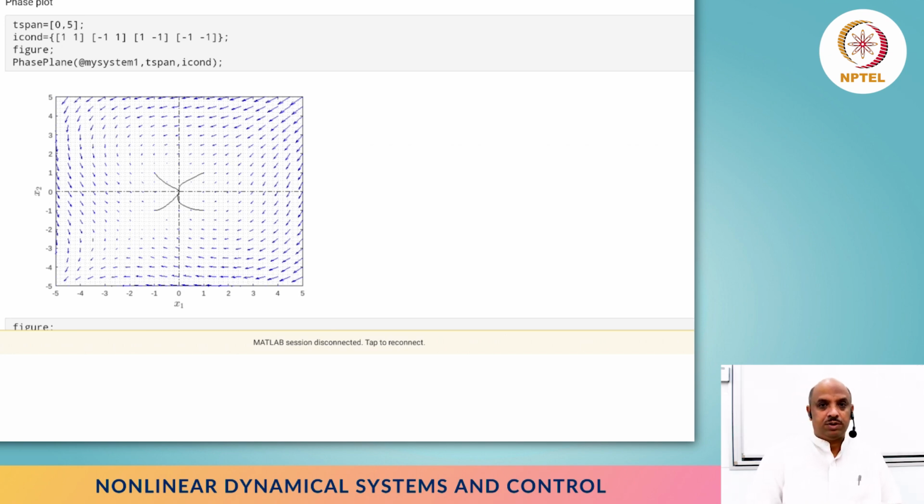If the linearization gives you Lyapunov stable, then we don't know much about it, we can't say anything. The only two cases that we are happy with are either it's Hurwitz, all the real parts of eigenvalues are strictly negative, or one of them is positive. Only in those cases can we conclude something about the nonlinear system. If it is unstable, then nice, nothing local or global, it's unstable. But if the linearization happens to be Hurwitz, exponentially stable, then we can conclude that the nonlinear system is also exponentially stable but locally, and therefore we will have the burden of understanding how much domain of attraction we have, and nothing can be said beyond this small domain of attraction.